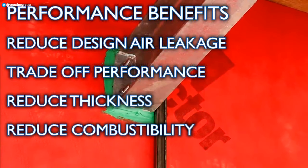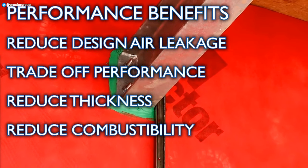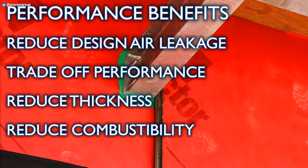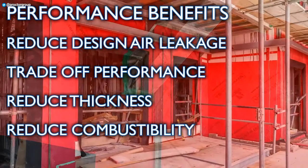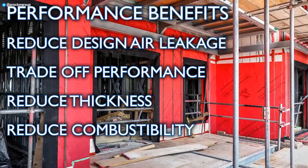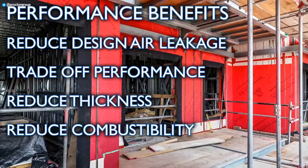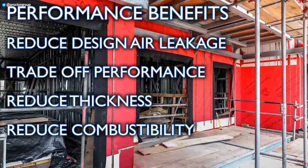In this case, however, the goal was not to reduce the thickness, but to switch from a rigid foam insulation to a less combustible mineral fibre product. Ordinarily, this swap would increase the thickness of the wall assembly significantly, but here, the reduction in emission rate delivered by wrap-tight allowed this switch to happen with almost no additional thickness.